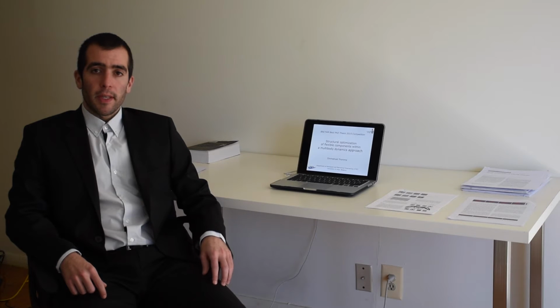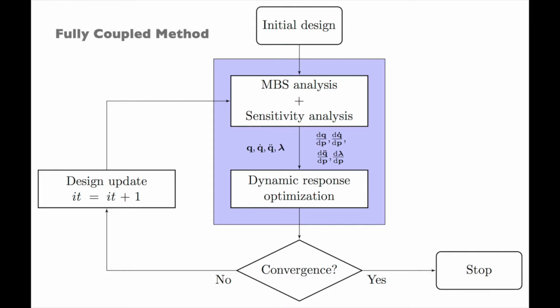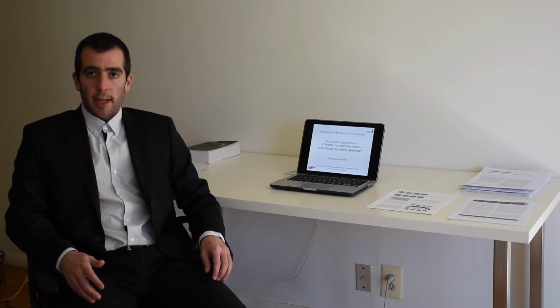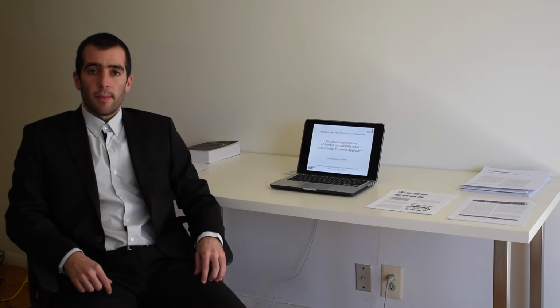The fully coupled method incorporates the time response coming directly from the multibody system simulation. On the optimization flowchart of this method, we can see that the multibody system analysis and the numerical optimization work in an integrated manner. Since the optimization problem considers directly the time response, we solve a dynamic response optimization problem.